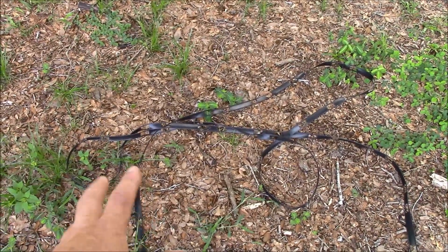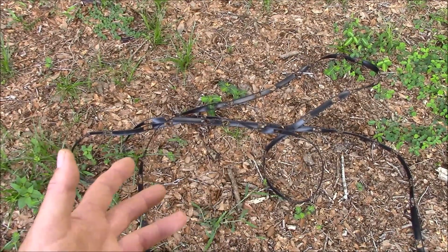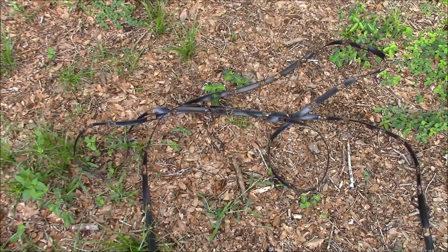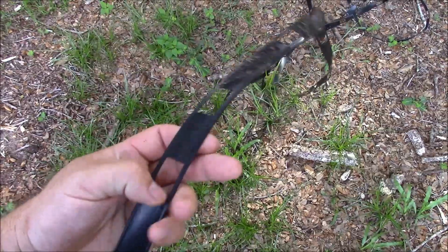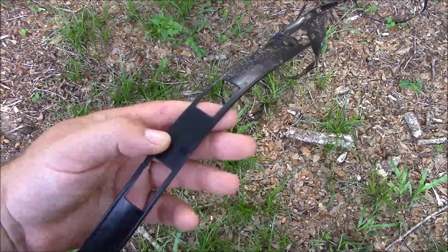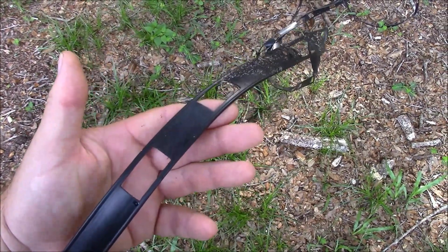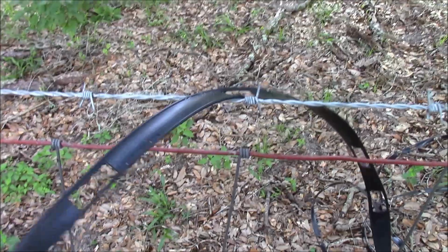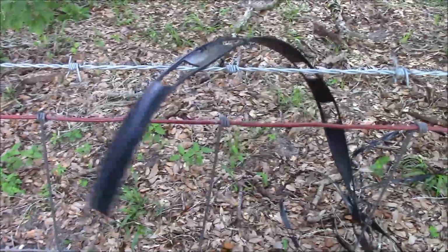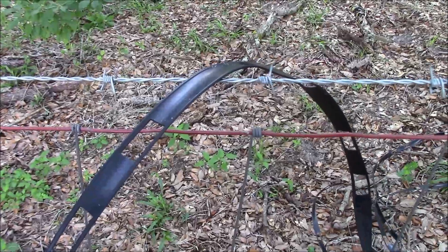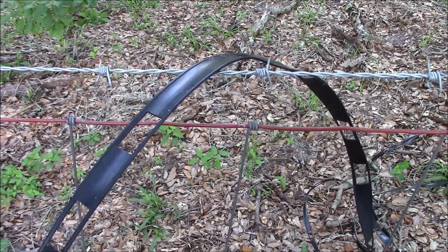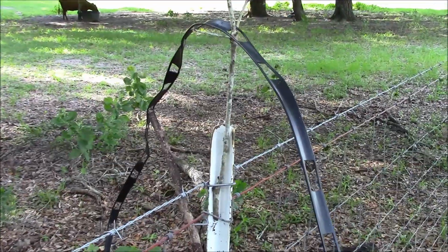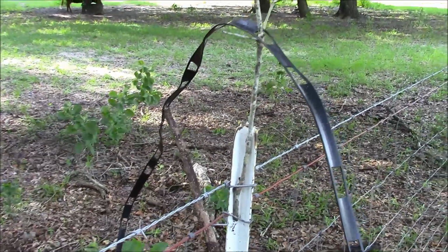And in fact, it's said that balanced feed line should not be laid upon the ground. I try to minimize that, but if some ground contact is necessary, I say roll with it. Balanced feed is sensitive to being wet, so oftentimes after a rainstorm, you're going to see your feed line change its characteristics somewhat. Balanced feed line should also be kept away from metal objects. You know, running it over something like this fence right here is not the correct way to route this. So even far from ideal, routing our feed line over this fence utilizing these field expedient insulators is preferable.